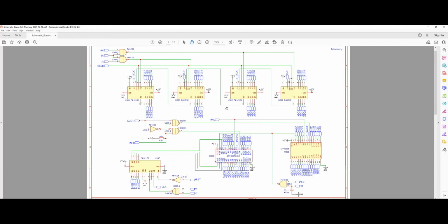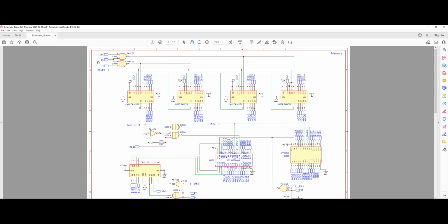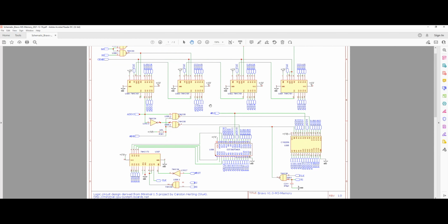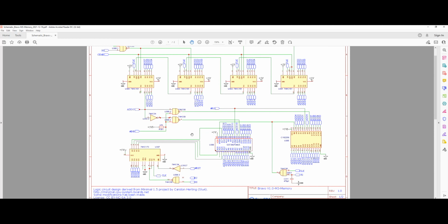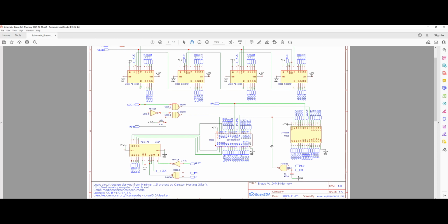Therefore, on the output side, we actually do not need the HI or inverted HI signals. Essentially, the whole 16-bit output of the circuit will be output in 1 clock cycle, connected directly to our RAM and also our flash memory. I hope that it is clear so far. Now, let's focus on the address lines and how we could actually address our memory and output or input a specific value into our memory.